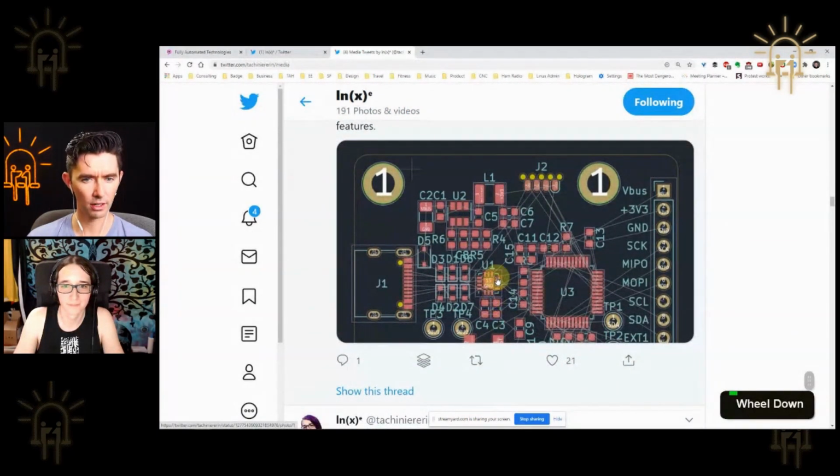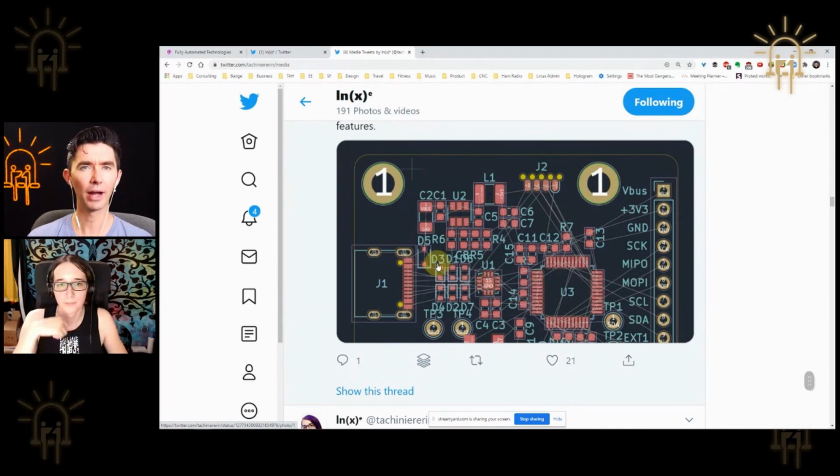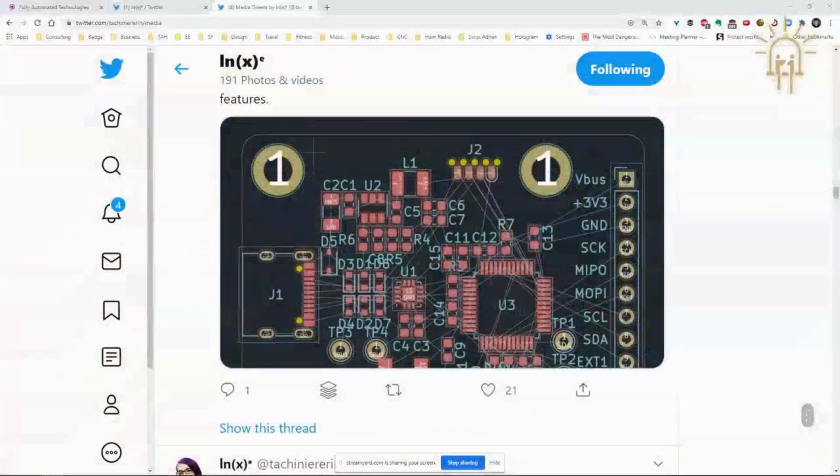And so the PD delivery, is there a certain chip? Is it this chip U1? Is that what's doing the actual handling of it, or how do you activate that PD capability? So U1 on the picture before was the FUSB302. It's a USB-C power delivery chip, which does the whole baseband stuff and does the time sensitive stuff of the communication part.